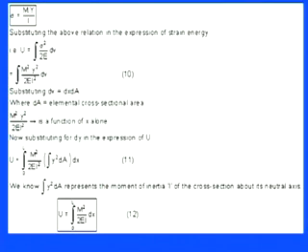These are the two key parameters through which we can say how much energy can be absorbed or put into that material: the applied bending moment and the flexural rigidity, that means the material properties. So U equals the integration from 0 to L of M squared divided by 2EI into dx. This is the form of the strain energy for the bending action. Now we would like to solve some numerical problems based on that.